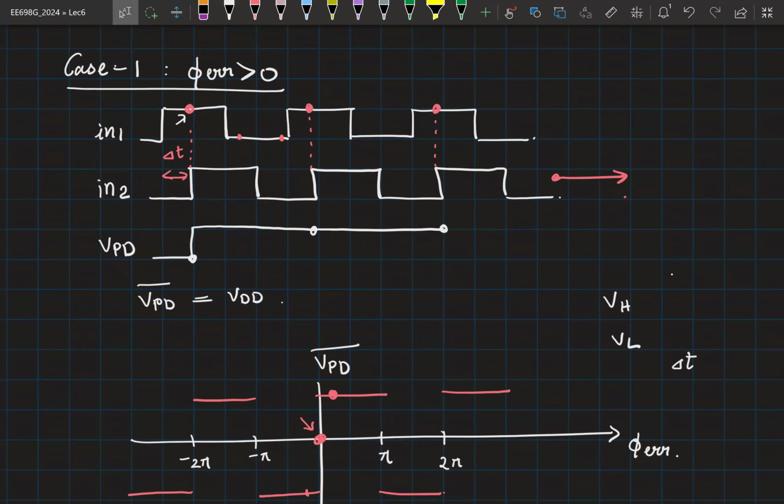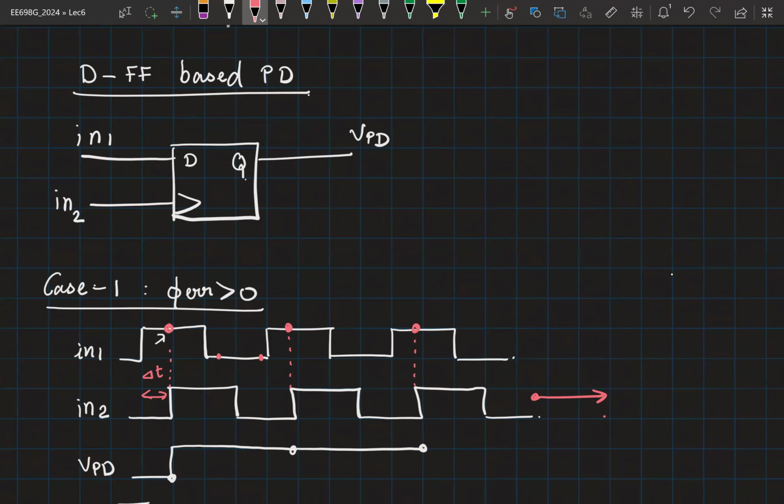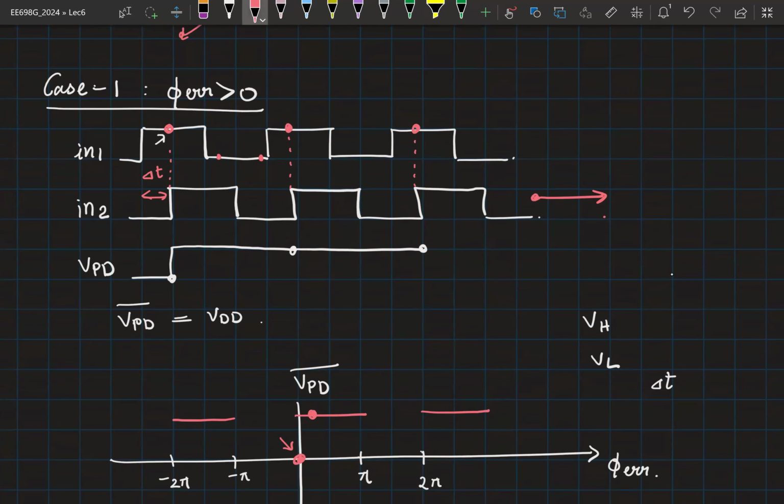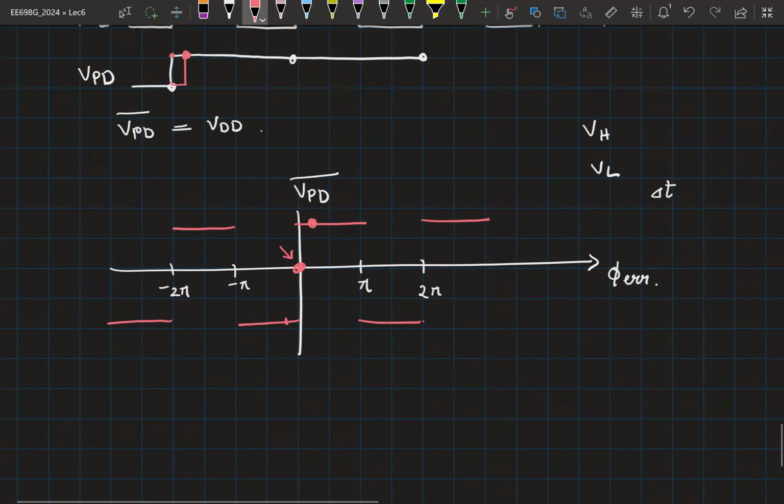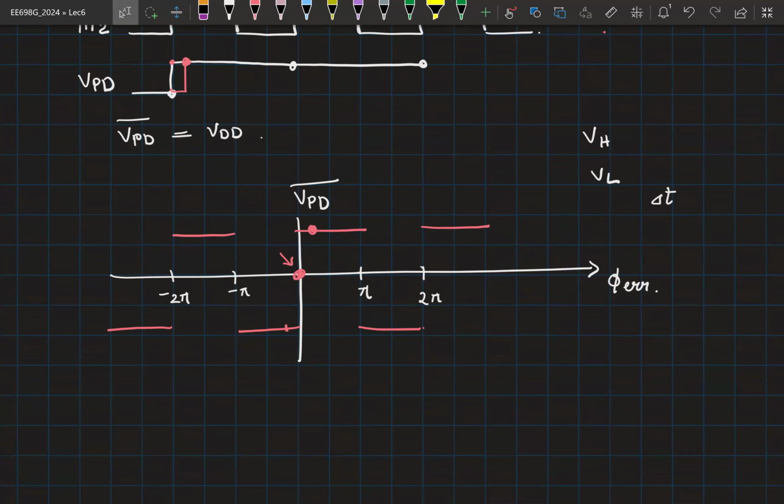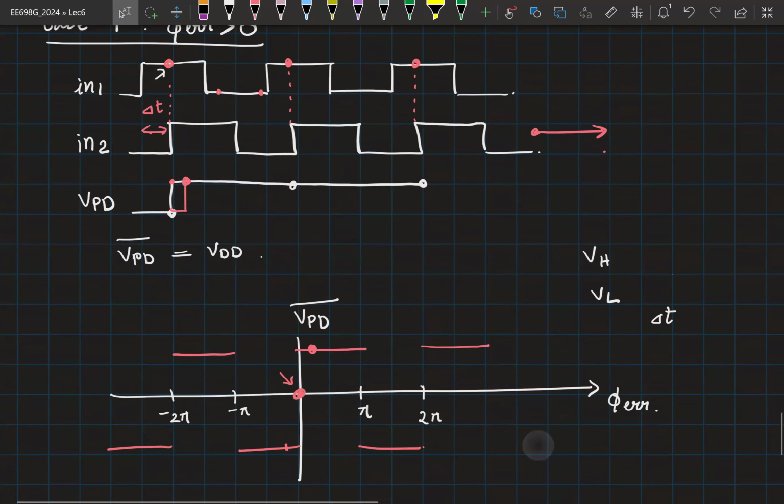Let us take a quick look at that answer, right? You're saying that if I consider the delay of the flip-flop, let's assume that I take a delay from clock to Q path, some TCQ, right? Which means after the input has occurred, the output is happening after TCQ, right? Then all that it means is that instead of the output changing here, the output is going to appear here. You'll simply have a delay. So I think the curve is going to get shifted to the right?